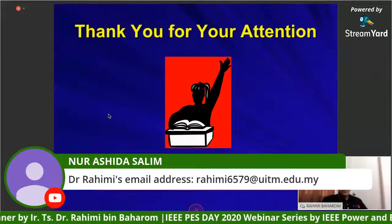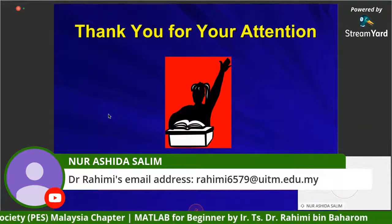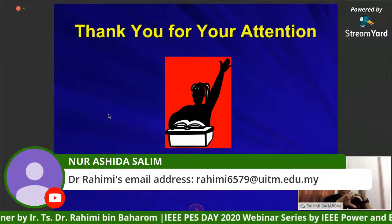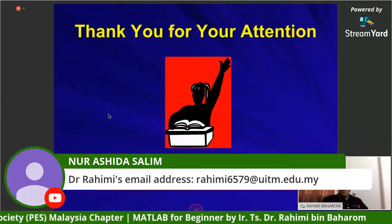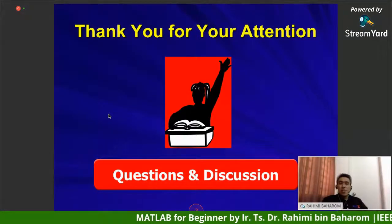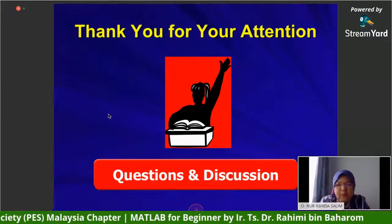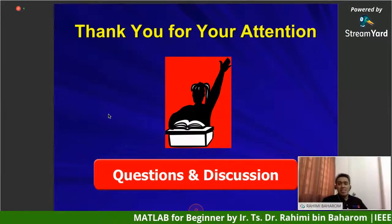Okay, another question. In my model, I can't connect a resistor with the AC source. If you cannot connect the resistor to the AC source, I guess maybe you used a resistor from the electronic tools, the electronic block set. You cannot interface between the electronic block set and the sim power system block set. So you have to select the resistor from sim power system, as I mentioned just now. Can I use more than one subsystem by this method? Yes, of course. You can create a subsystem under a subsystem. No problem.